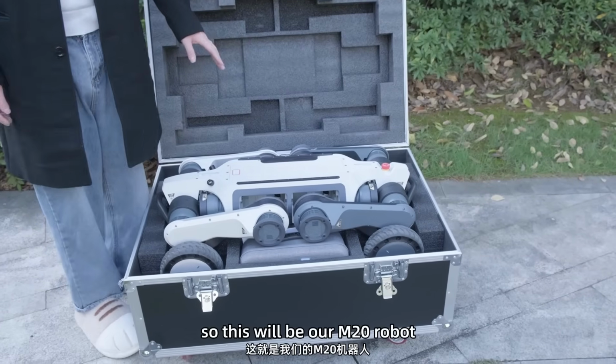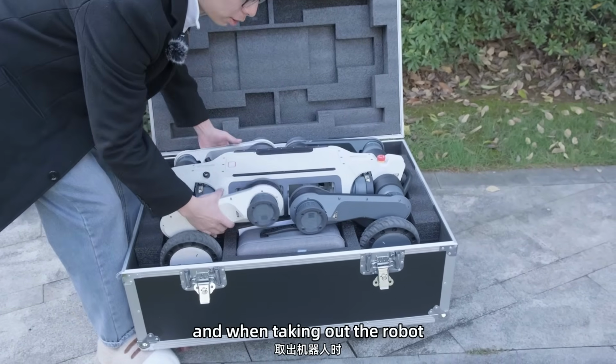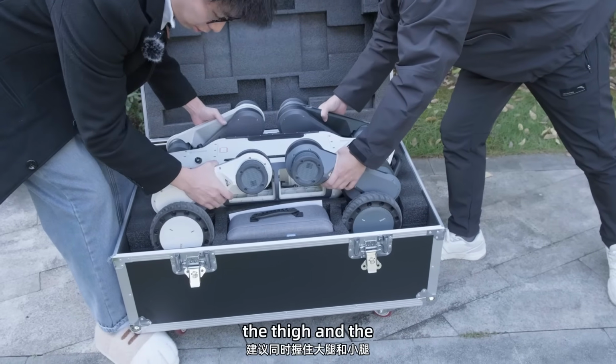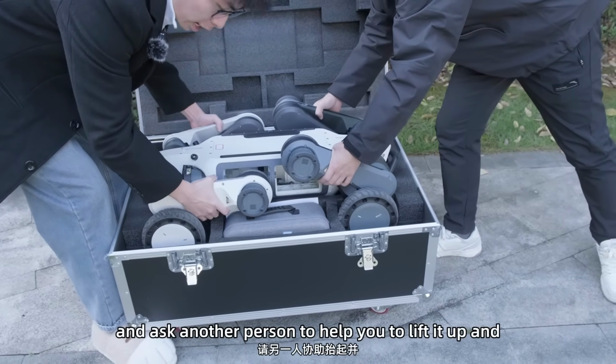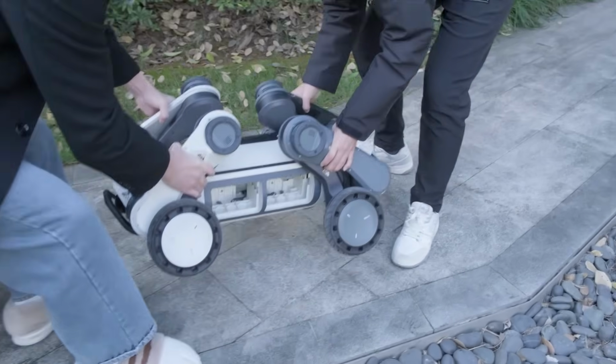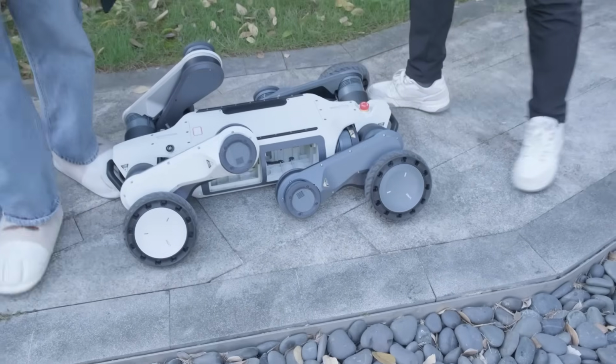So this will be our M20 robot. And when taking out the robot, I recommend to hold 2 legs, the thigh and the shin together, and ask another person to help you to lift it up and put it on the ground.